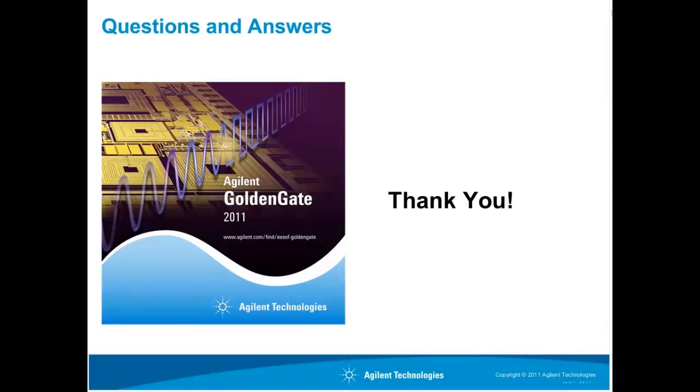I guess the key difference is that GoldenGate natively sits within Cadence Virtuoso ADE and runs advanced harmonic balance simulation and circuit envelope types analysis directly in Cadence without having to leave that platform. And the flow and methodology that Paul described today allows a Cadence Virtuoso user that's taking advantage of GoldenGate to export these models into SystemVue for verification.